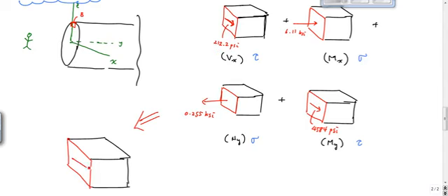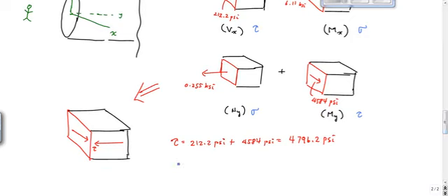And then, so now I got to say, my shear stress here, this tau, is equal to 212.2 PSI plus 4,584 PSI, which is 4796.2 PSI right there. That is my tau. Bam. Okay? Now I can draw the rest in. That's my tau here. And my normal stress, sigma, which I'll do in, how about blue?